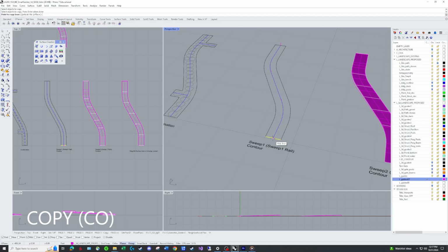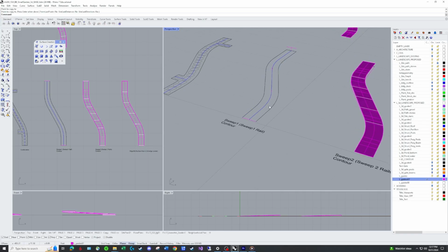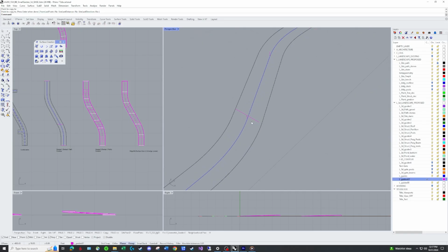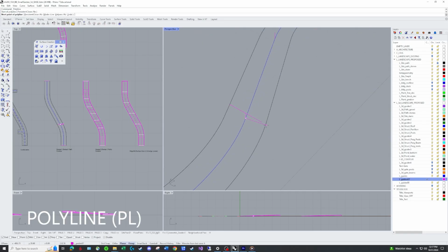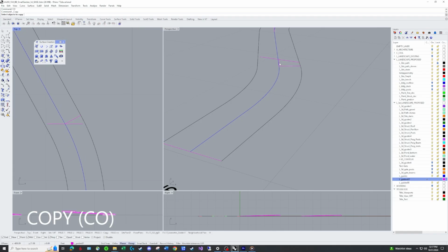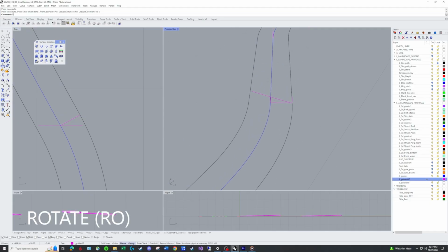We'll copy this curve because it doesn't know to go vertical here unless I give it the cross section or the sweep shape. So I have to do that here as well, but this is at the wrong angle. What I need to do, and this is easy to do without making this guideline, but I just want you to see, is make sure I'm perpendicular to this pathway. So as it makes the curve, the cross section is also operating at that same angle or perpendicular.